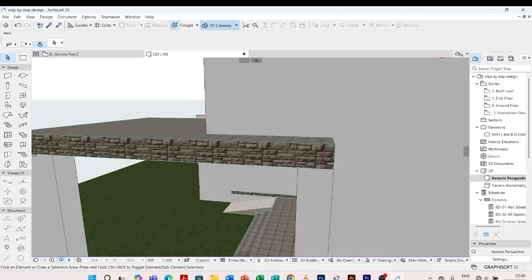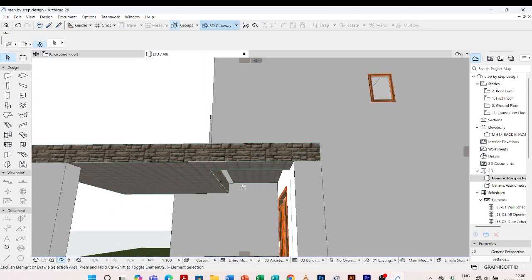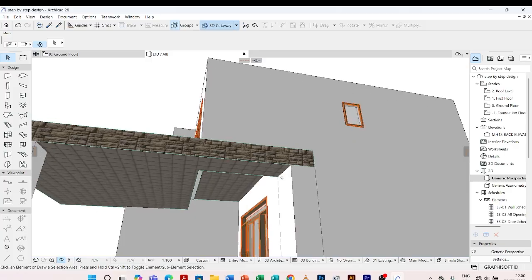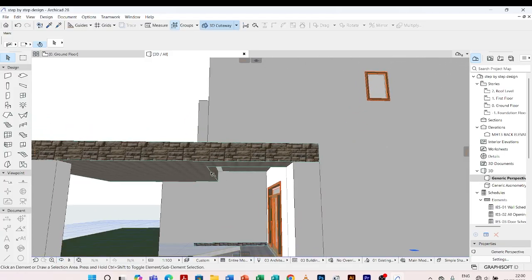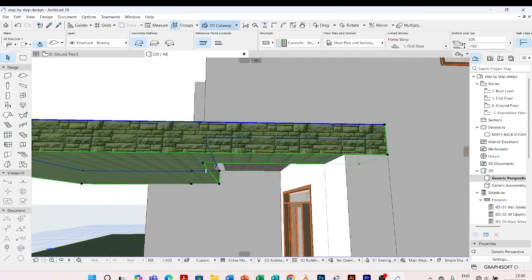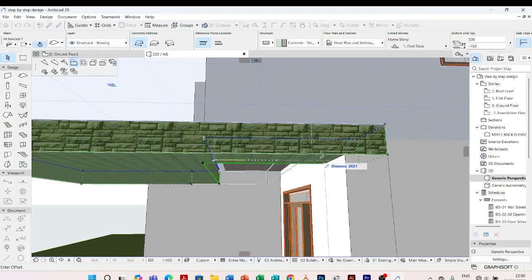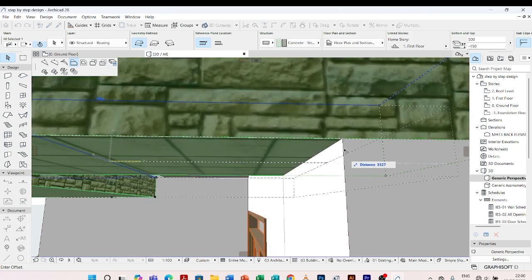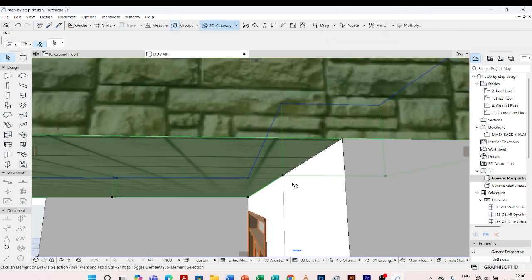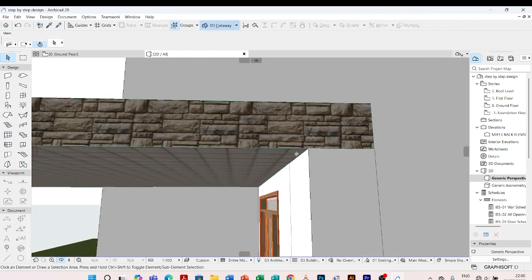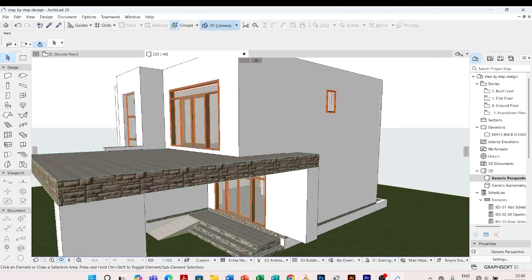In the same way, I need to offset it also under here. So I'll come, pick this. I come to the blue line up, click on it. It is already in offset edge. Hold on to Shift. I'll offset it at that point. When I rotate, this is what I have.